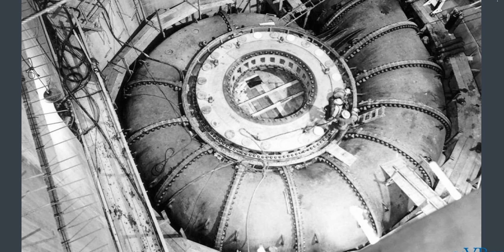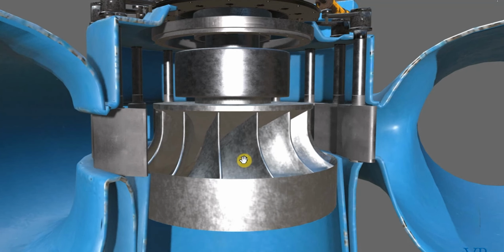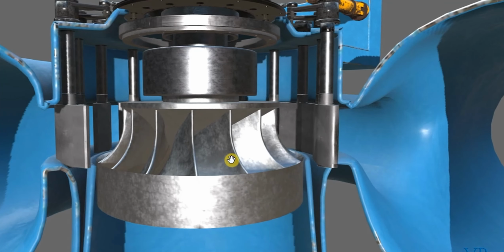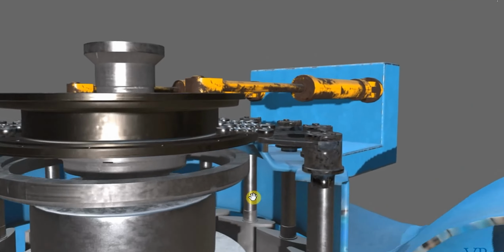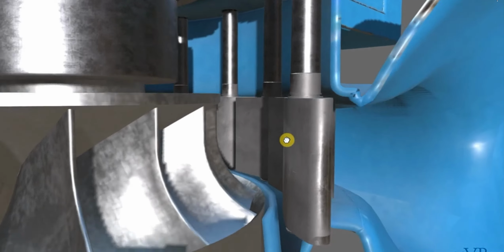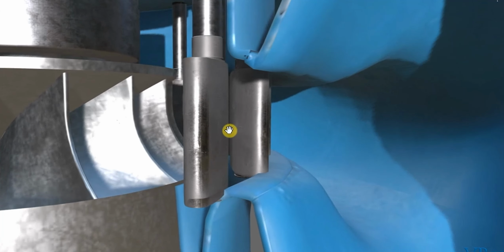So we're not getting a huge influx of water that just flows into the runner on one side. That would cause an imbalance, potentially vibration, which may even damage the runner. Not only that, but the runner is going to operate inefficiently. We use a wicket gate to feed the water into the runner. This is our wicket gate here.